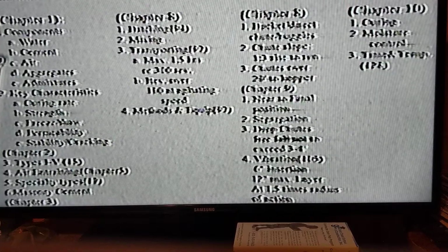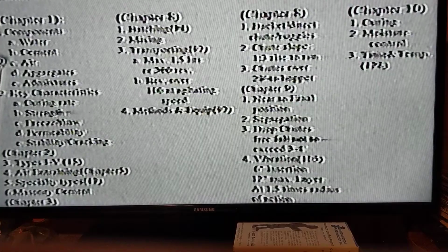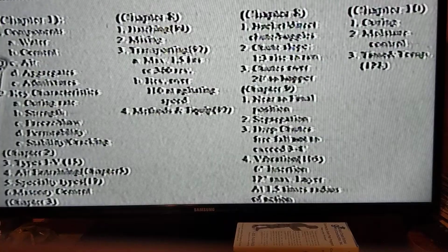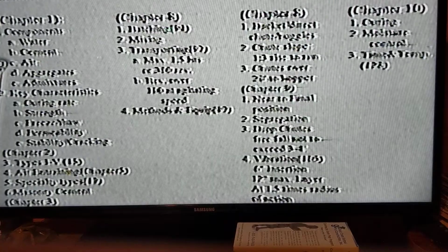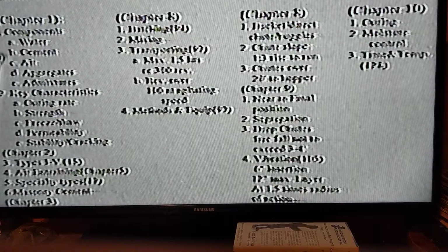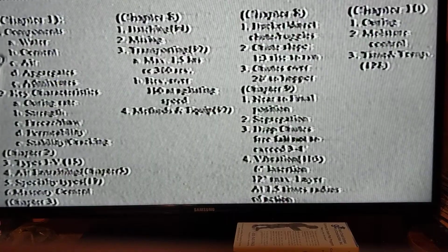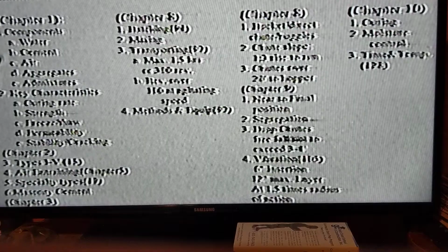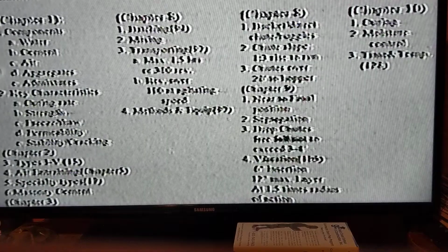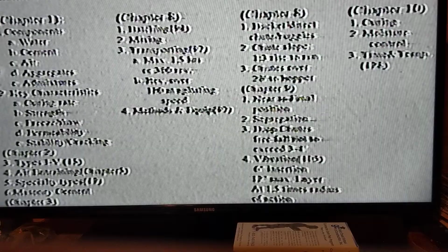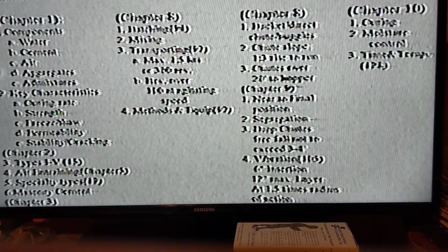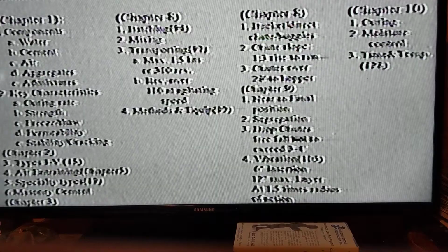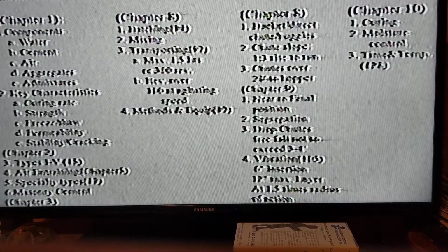In the second condition, where I had 2 units of water for every 1 unit of cement, would you expect that concrete to be softer or harder? It would be softer. It would be soupier. And therefore, the higher the number in the water-cement ratio, the weaker the substance. Another component is air. We've talked about air before. It provides insulation. It makes the concrete more plastic, which therefore resists freezing and thawing and resists cracking.